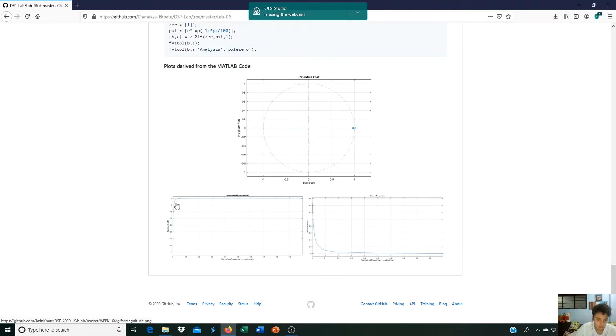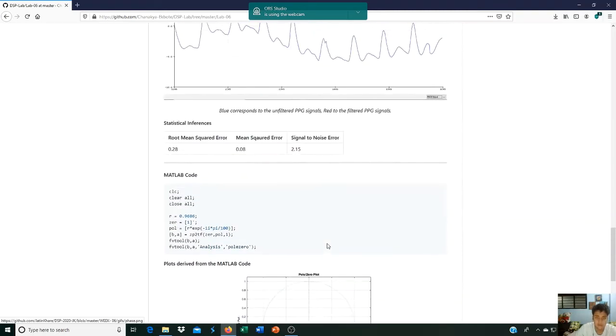Although you can't see it here, a lot of things get filtered out by this particular filter. Note that this 0.1 doesn't correspond to 0.1 Hz. It is actually much higher than that because this is a normalized frequency. This is plotted in dB, and 0.1 Hz corresponds to this value. 0.25 Hz corresponds to a value around this point. Hence, it gets severely attenuated at this point, and hence this is the ideal magnitude response.